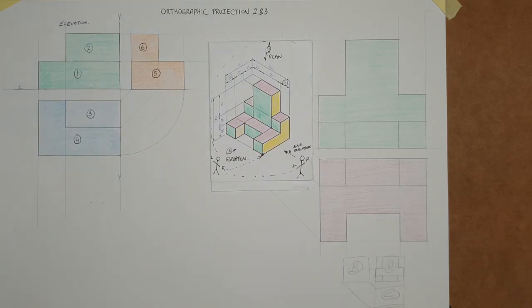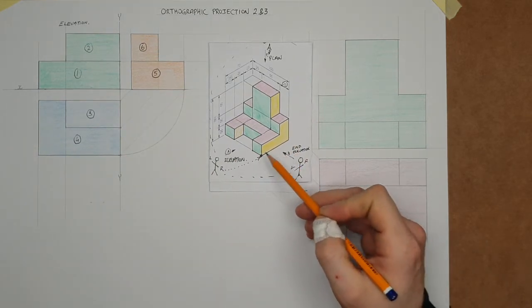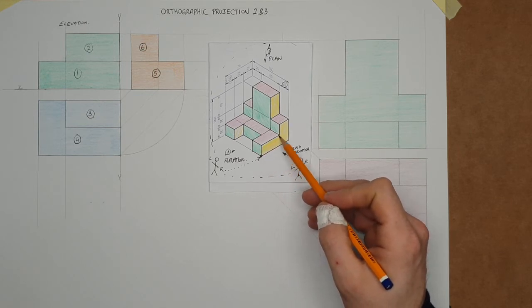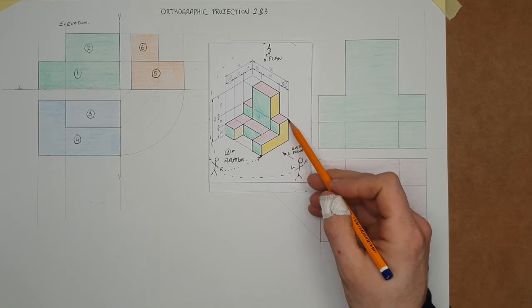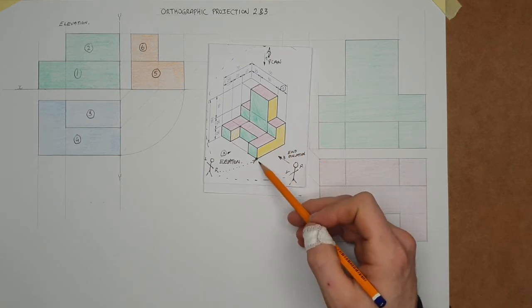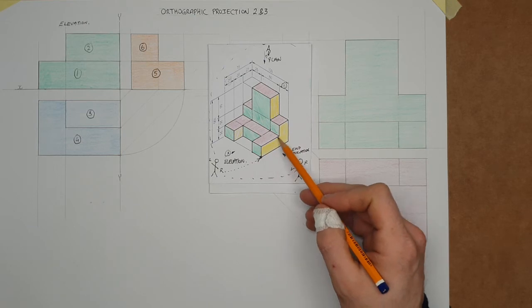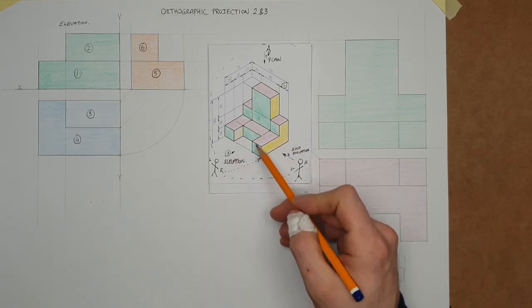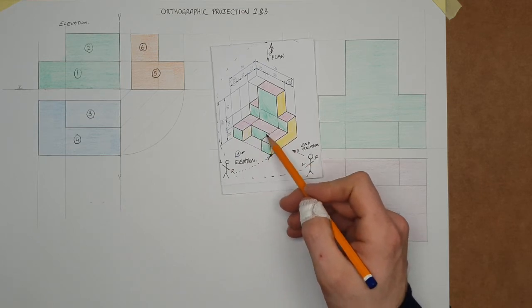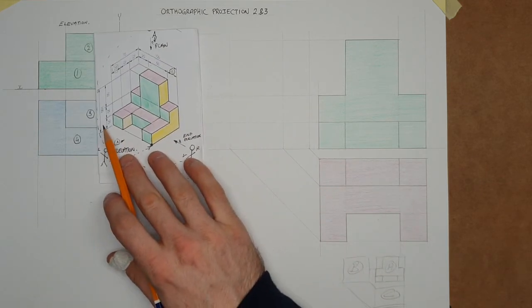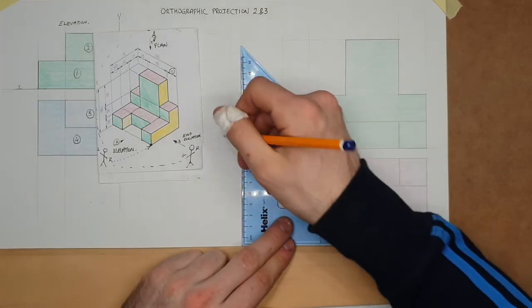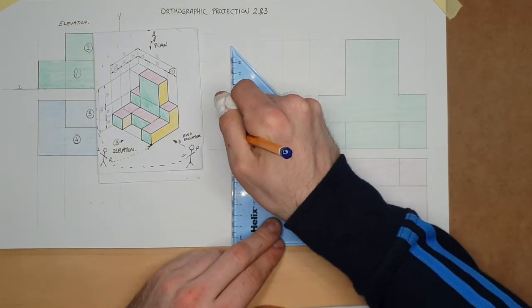Now, let's have a quick look at the question again. When we're in the position B, the left hand side we can see 25, then it goes along by 50, it goes up 25, 25, down by 50. Basically from our left to our right we can see this L, left to right. The low point is at the front of this U shape. So if we work back down to plan, the low point is here. So make sure we do that one correctly. We don't want to turn our view the wrong way. The low point here.